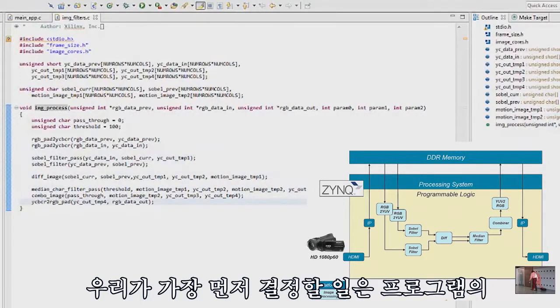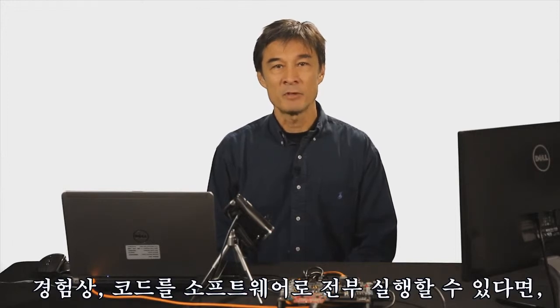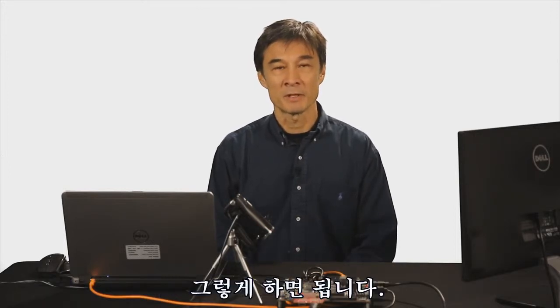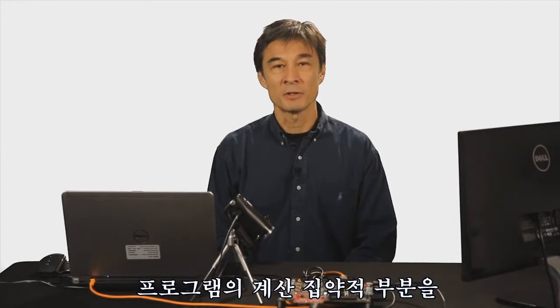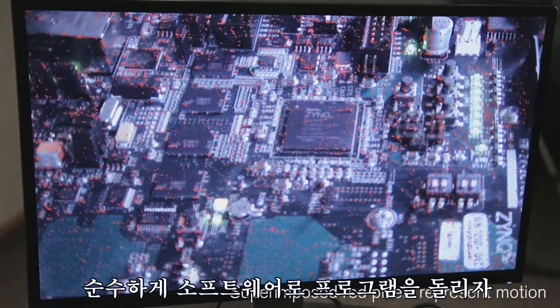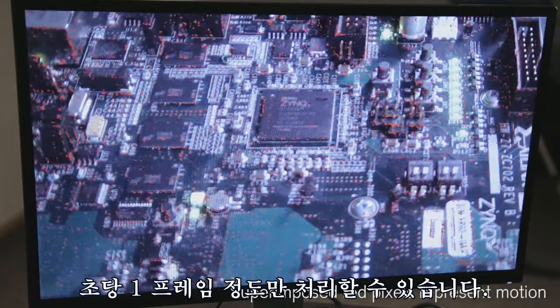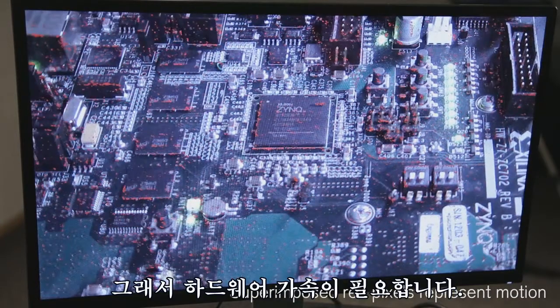Now our first task is to determine which parts of the program should be compiled into programmable logic. As a rule of thumb, if you can run your code entirely in software, you should. But when you need more performance, you can offload compute-intensive portions of your program into hardware. We ran our program as pure software and achieved only about 1 frame per second, so we definitely require hardware acceleration.